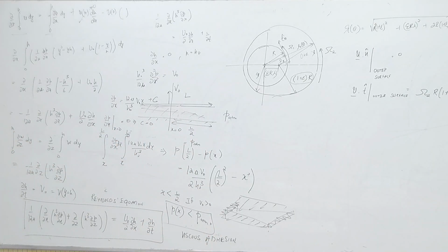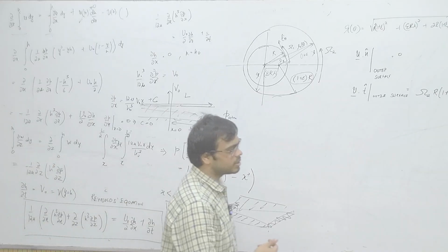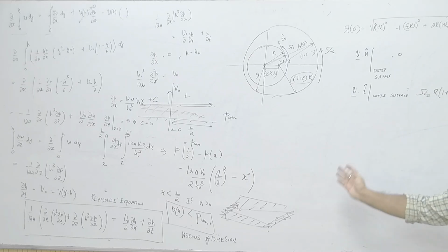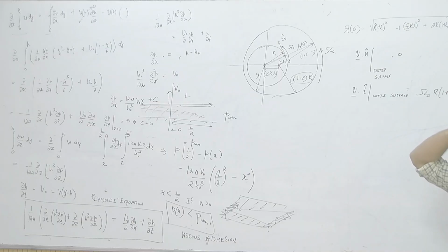And so, to just summarize what we have covered in low Reynolds number flows, we started with the non dimensionalization, we looked at the dimensionless Navier-Stokes equation, we applied the Re much less than 1 condition, and then we saw that basically viscous stresses and pressure have to balance each other out in the governing equation. Once you derive that, we followed flow past a cylinder, flow past a sphere.